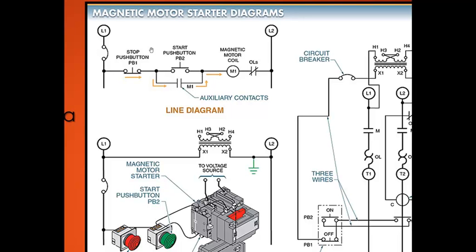But now say your motor is running in a high ambient temperature, or it's running slightly over its rated amperage. These overloads are designed to protect the motor against those situations. So if a motor is running for a period of time over amperage or in high ambient temperatures, these overload contacts will open, breaking the path of current flow, stopping our motor starter, which stops our motor.